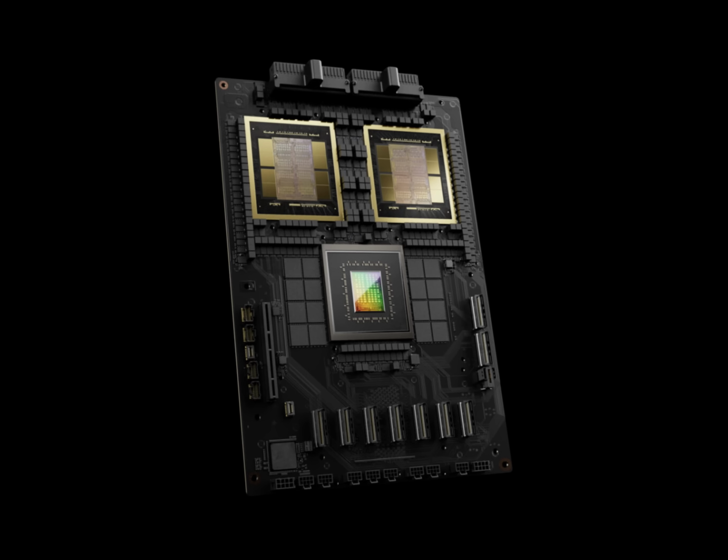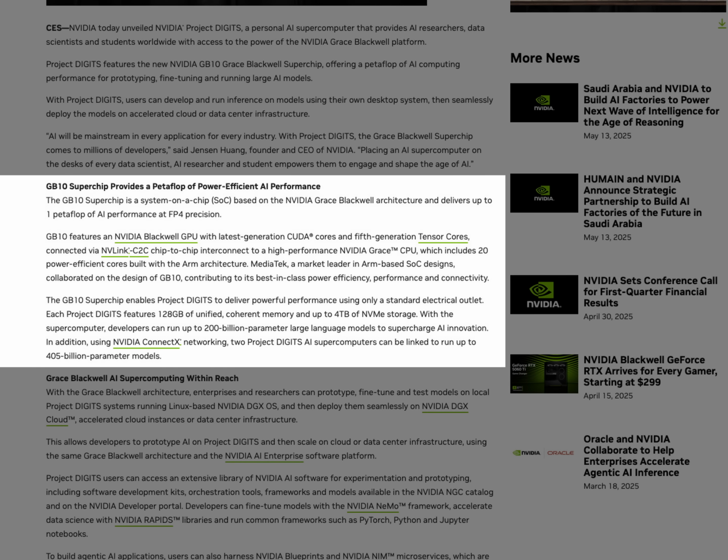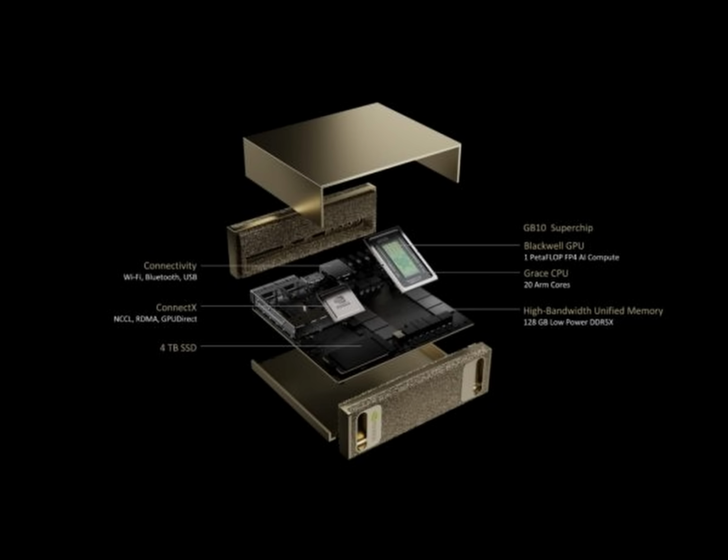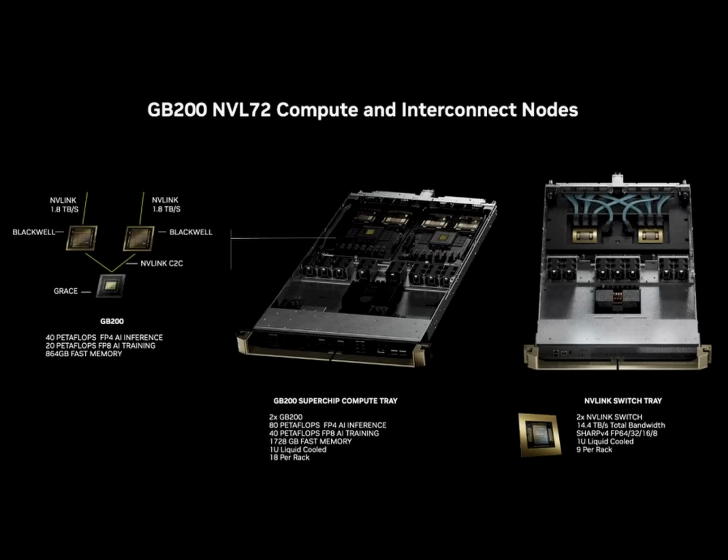In the cloud, the Grace Blackwell Superchip combines NVIDIA's Blackwell GPU architecture with the ARM Neoverse-based Grace CPU. The design optimizations that have come from this have reduced energy consumption by 25% and provided a 30x increase in performance per GPU compared to the NVIDIA H100 GPUs on their own. That's a lot of horsepower and some serious shrinkage in hardware required for it. The flexibility of the ARM Neoverse platform allowed NVIDIA to implement their own high-bandwidth NVLink interconnect tech, which you may recognize from running multiple GPUs in a consumer desktop system, but in these cloud systems allows massive improvements in data bandwidth and latency between CPU, GPU, and memory.